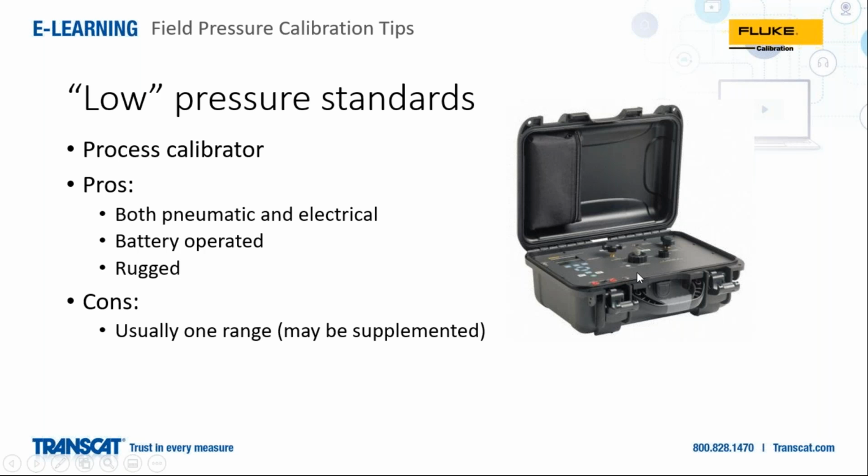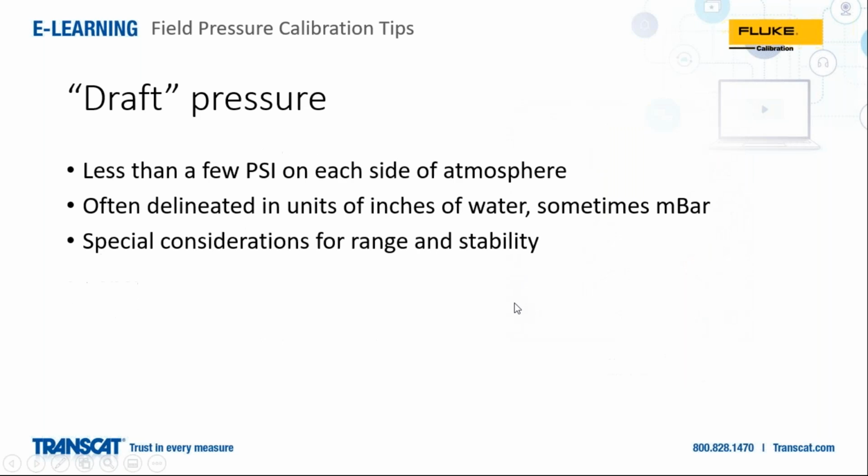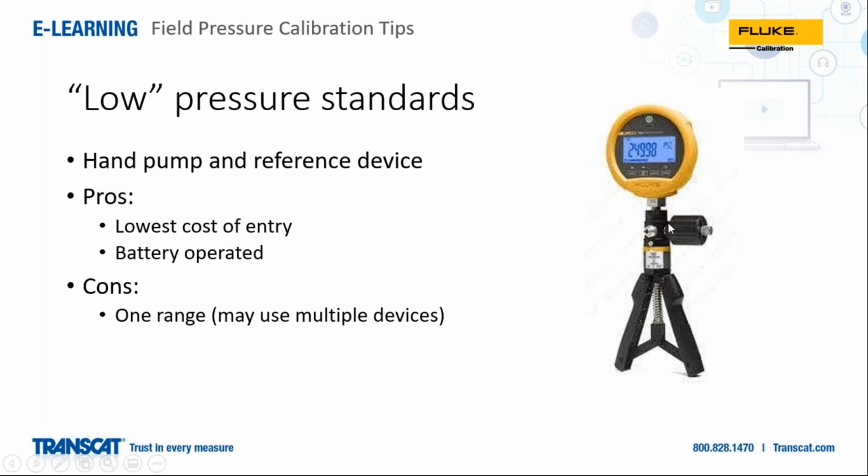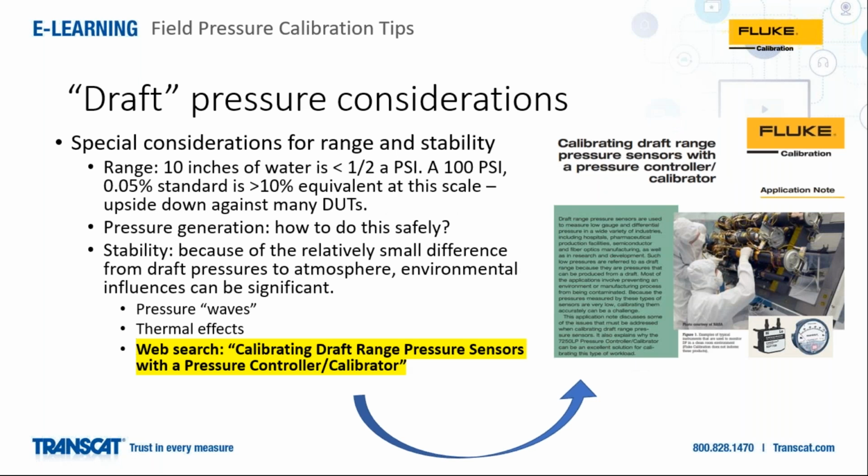However, it has a fine adjust knob on it, which allows the pressure to be dialed in. Same thing on these process calibrator pumps, by the way. Same sort of a knob here to fine tune the pressure. What that does is connect to a little piston inside the unit that moves in or out of a small volume, which allows for finer adjustments of pressure.